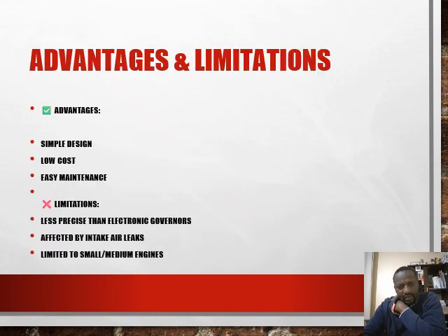Now, lastly, we would like to look at the advantages and limitations. The advantages are that it's simple in design, it is low cost, and has really easy maintenance. Its limitations: it is less precise than, of course, electronic governors, and it may be affected by air leaks, if the intake manifold has punctures or gaskets that are leaking. It can only work very well with small and medium sized engines.